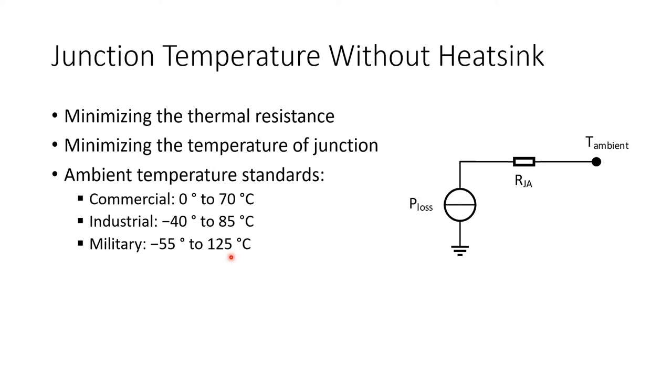So what we are trying to do in thermal calculations is to minimize this thermal resistance, because if we minimize the thermal resistance, the junction temperature will be the same as the ambient temperature. So our switching device can operate without any problem.